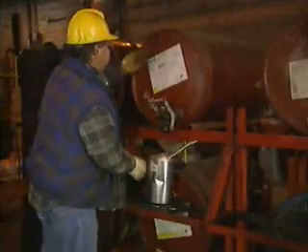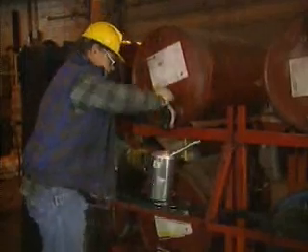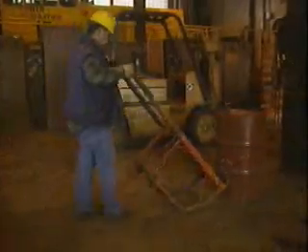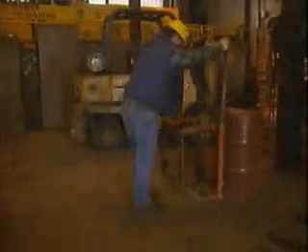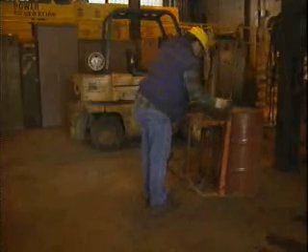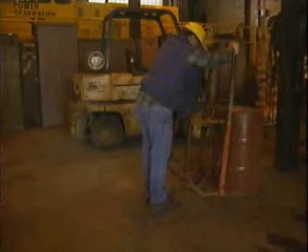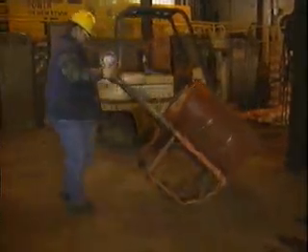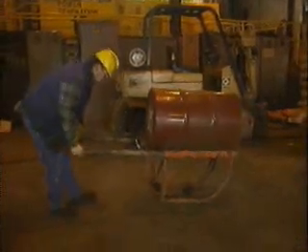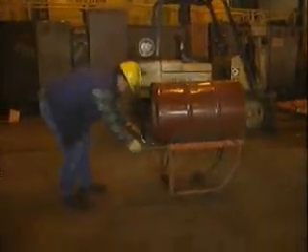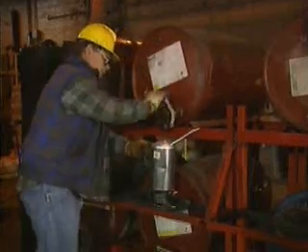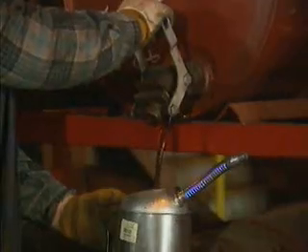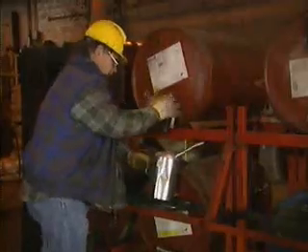Another way to dispense oil from a drum is with a spigot that has a leak-proof valve. The drum must be positioned on its side. Sometimes, a drum with a spigot is placed in a rocking frame. To dispense oil from the drum, the frame is rocked forward so the drum lies on its side. The drum may then be left in this position until it's empty, or if necessary, it can be rocked back into the upright position. With the drum vented, open the spigot and withdraw the oil from the drum. When the desired amount of oil has been withdrawn, close the spigot and the vent cap.